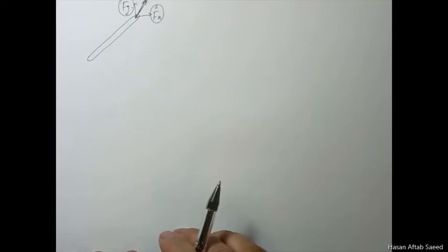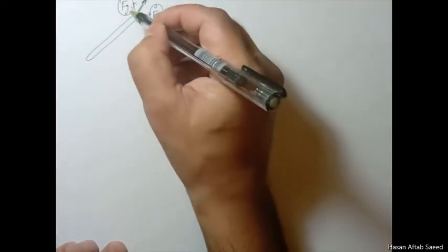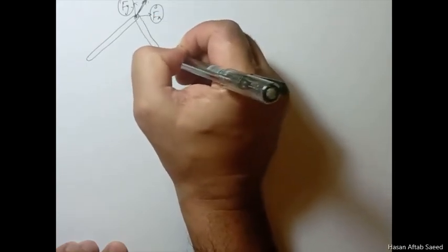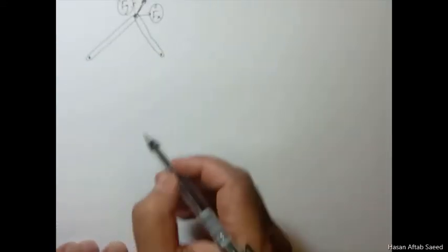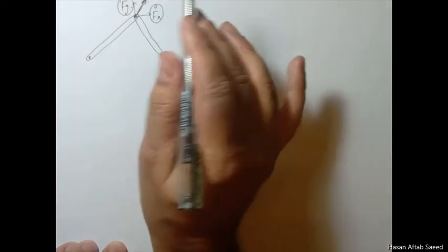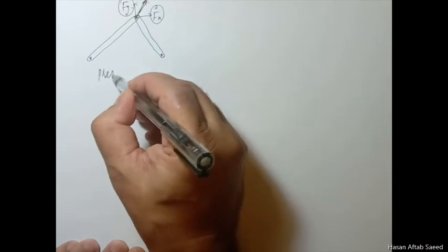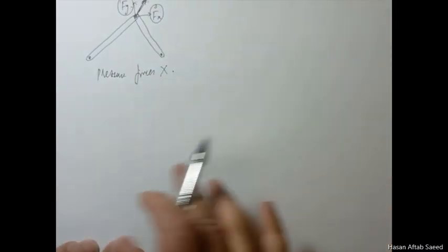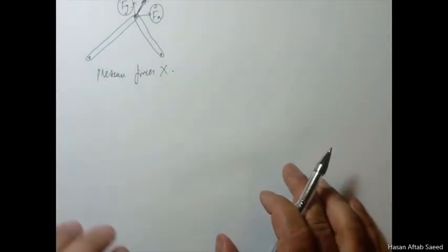But are there any other forces that are applicable in this case? We know of concentrated forces, we know of body forces, we know of pressure forces, and then thermal forces. Now, pressure forces are again not applicable here because it's a pin jointed thing. Here there will be another element. The only legitimate way for this analysis is to apply the forces by using these pins. So pressure forces are out, so we don't need to worry about them, because if we include them, then our initial assumptions are violated, so this analysis is not for them.